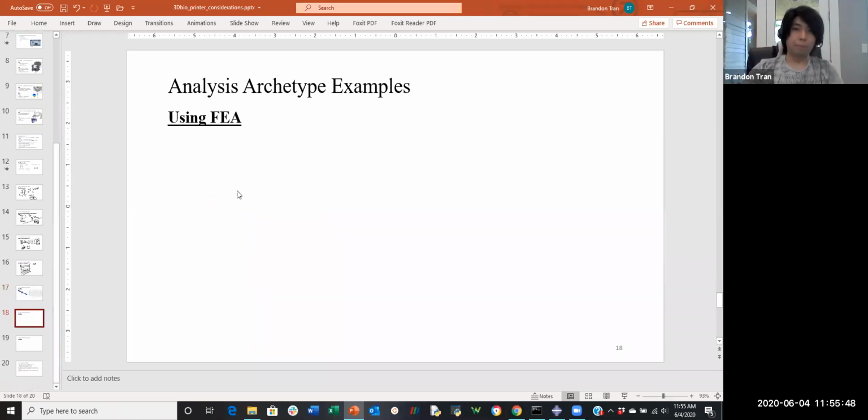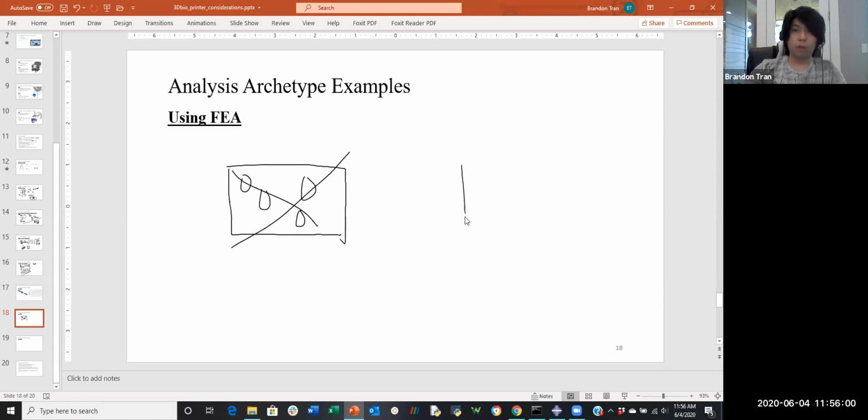But in finite element analysis, for example, if I have a plate with multiple holes like this, something complex, you would not analyze this first. You would start off with something simple, a plate with a singular hole in it. You would analyze this and see if your analytical solutions match whatever stress concentrations you find around here or here.